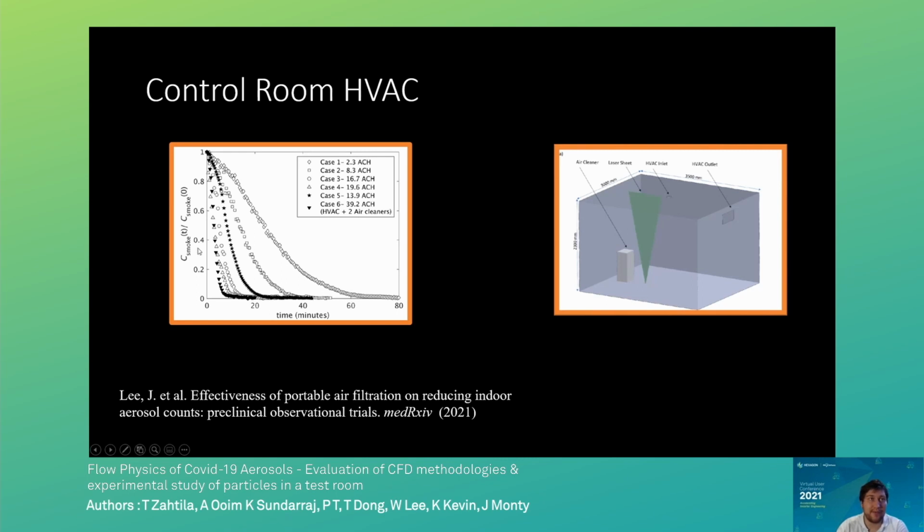And if you wanted a good shot of no particles in your inhalation, so if you want a 97% decrease or something like that, you'd probably need to wait an hour. And that's that curve there. But what we found was if you put in these air cleaners that suck in air and filter it, so they remove the particles from the system and just blow back fresh air, you could dramatically decrease that time. So now we're talking 40 minutes or less, and as you put in more of those air cleaners, you're actually able to remove the particles more and more quickly.